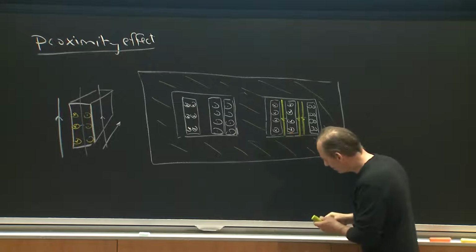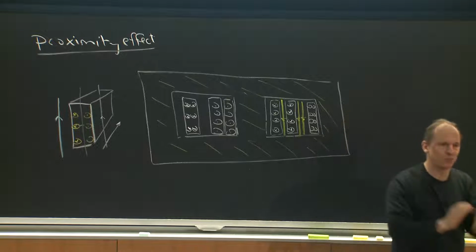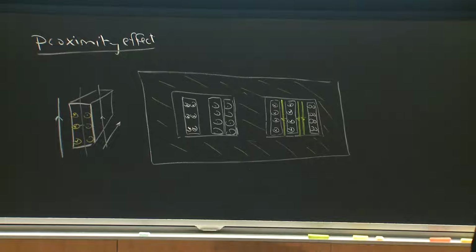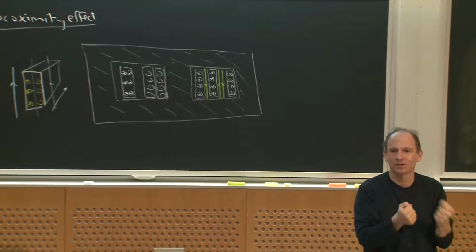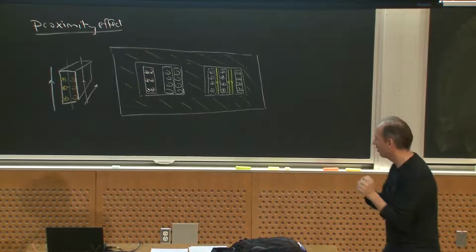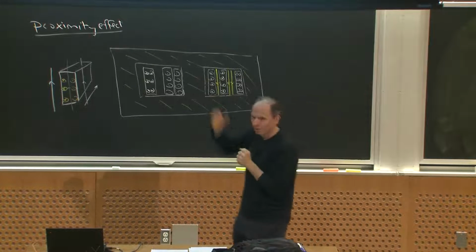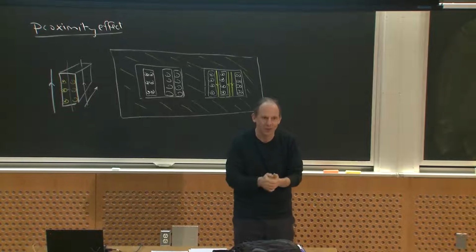Okay? And the problem with that is, especially if I have very many layers of winding, and I have very high AC current components, that induced loss gets reflected, and the way it looks electrically is a much higher AC resistance to the winding. So you could calculate your theoretical DC wire resistance, and say it's 10 milliohms.